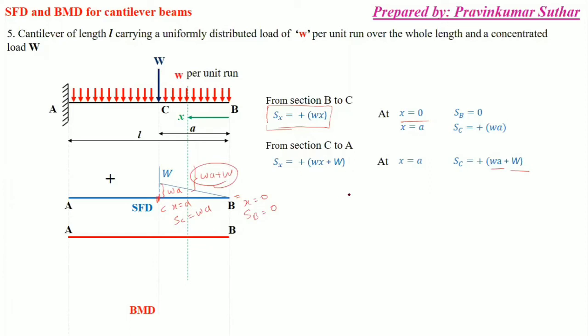Then again, moving from C to A, at x equal to L, this value is wL plus W. So like this, this is the maximum shear force, that is small wL plus capital W in this case.